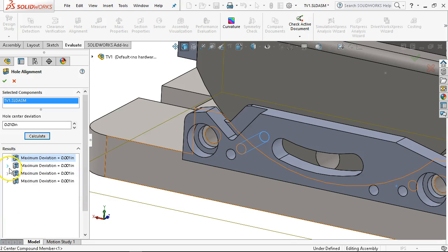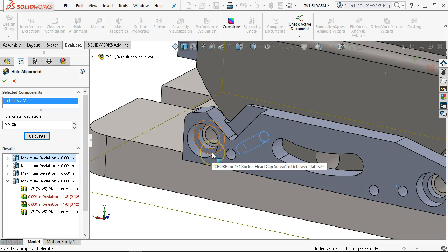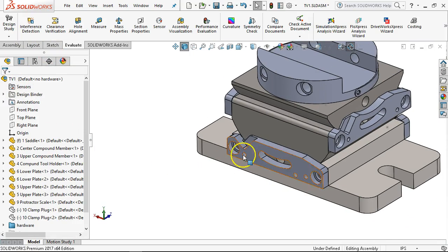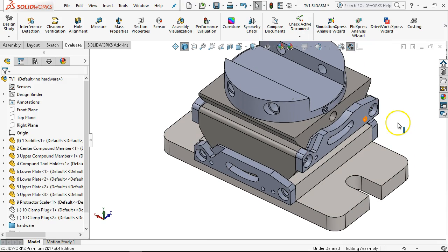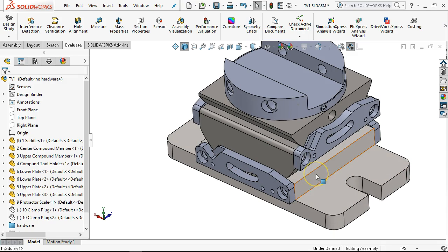All right, so same thing on the various parts. It's all revolving around the tight tolerances around those 1/8 inch holes. So having that come up in the hole alignment, that's something I'd go back and take a second look at and do a reality check. Am I confident that I can press that pin in, and once it's pressed, those parts are pretty much together forever? Take a hammer to get them apart.